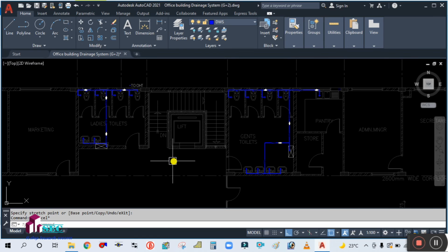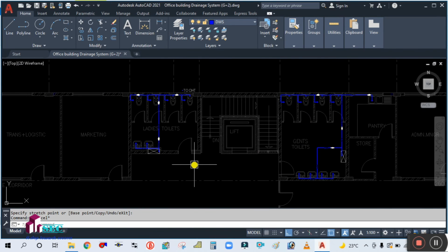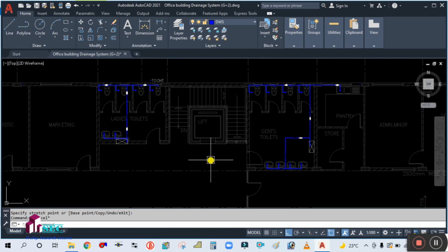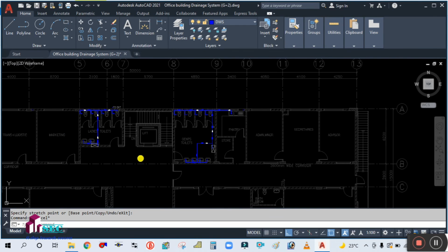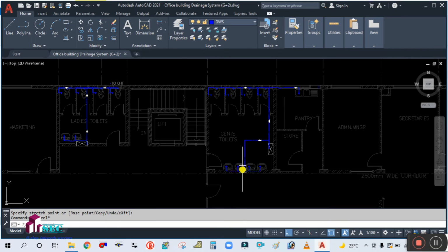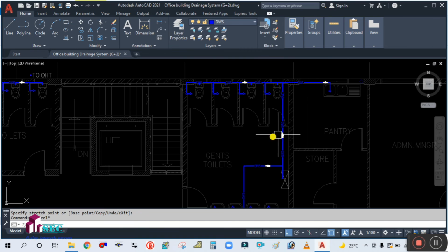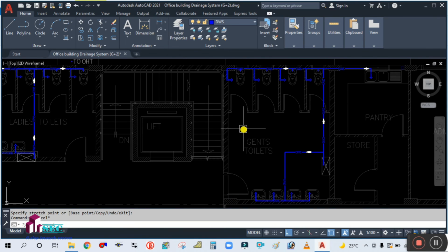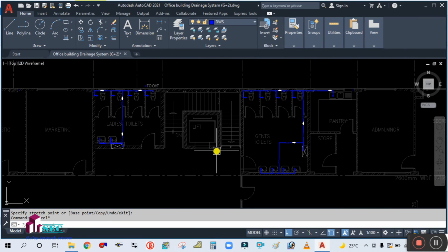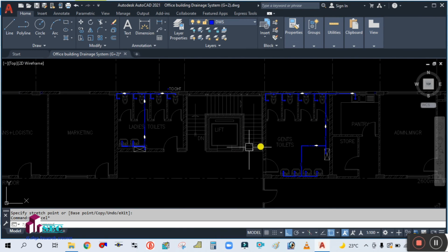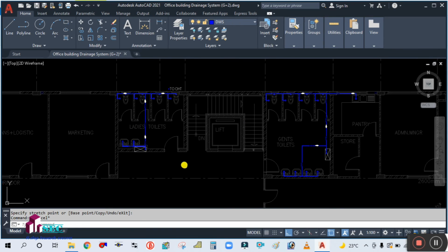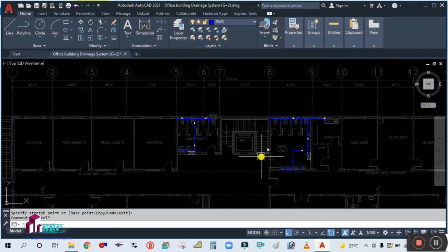And the three pipe system is nothing but the STP, sewage treatment plant. Okay, so in that system, the waste water will be coming from these laboratories and hand spray, bathtub, will go to this tank, sewage treatment plant, and then it will go to this grey water tank after treating. This water will be used for the flushing purpose. Okay, so there will be a grey water tank.